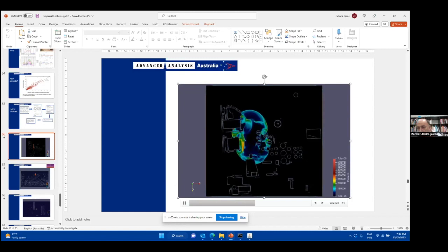So you remember we calculated 2.5 bar using the multi-energy method. It is about 4 bar here, and with other CFD models it was about that number as well. So that's the Buncefield case.